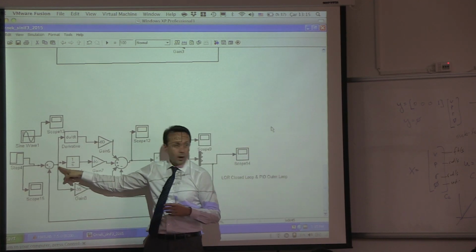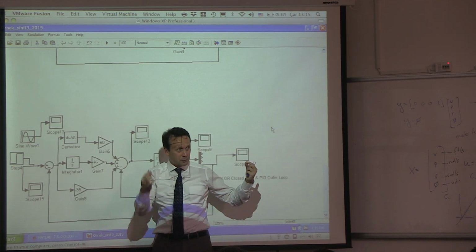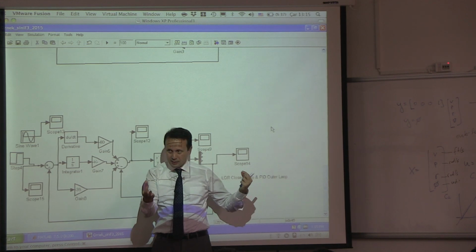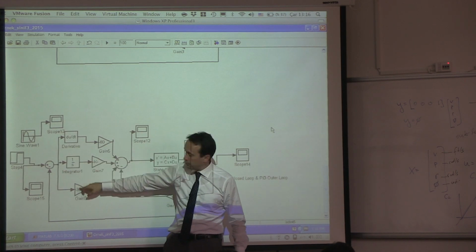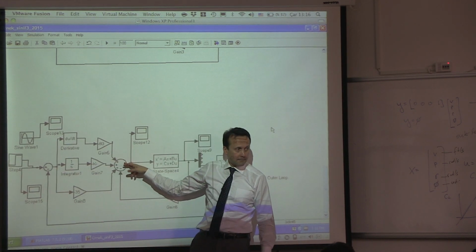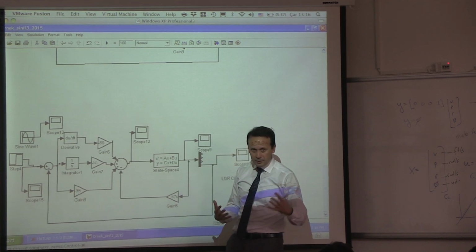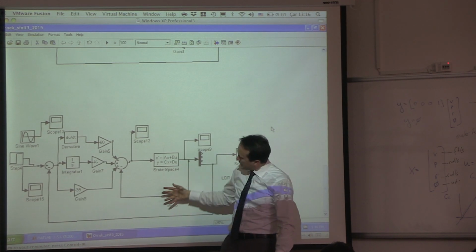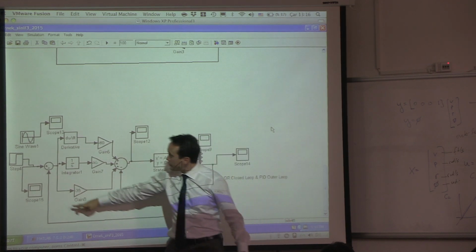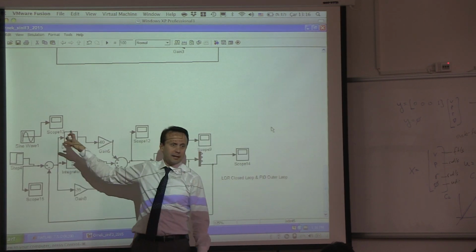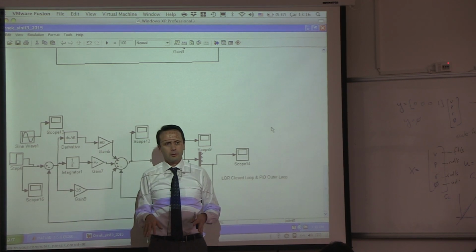Okay? So this is you're feeding back the whole state. Here you're sending in one number. Therefore, AE483, classic control is single input, single output system. That's why I was telling it is a single input, single output system, because you need one single input so that you can take the integral, derivative, and proportional and send it over. Okay? But this is full state feedback. So typically what we do in controls problems in aerospace, we would stabilize the system with full state feedback, like in modern control, and then wrap around these loops to control other things, to track things, velocities, angular positions, and so on and so forth. Understood?